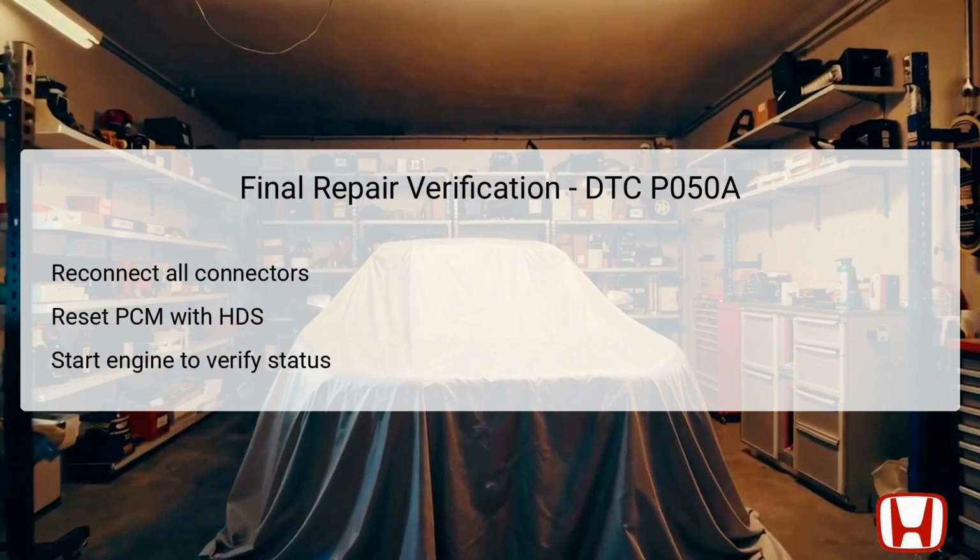The final repair verification is a crucial step to confirm that all issues related to DTC P050A have been effectively resolved. Start by reconnecting all connectors that were previously detached during the troubleshooting process. Next, perform a reset of the Powertrain Control Module, PCM, using the HDS, which is integral in ensuring that the system operates under the latest conditions set after repairs.